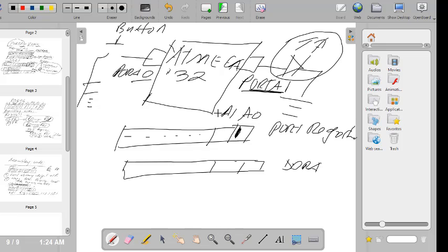And port A1, I want to give it a low status because before the button is pressed, I don't want this LED to come on, right? So I'll give it a 0 status. And here I'll give this input port a 1 status for a reason that I'll explain later on. Right now, I'm just showing you to understand the basics of how the direction and the status work.